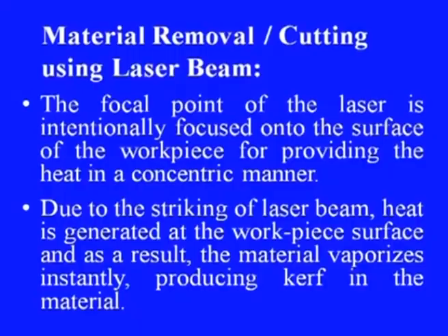It means the focal point is the point where we want to make a cut or make a hole in case of drilling. Due to the striking of the laser beam, heat is generated at the workpiece surface. As a result, the material vaporizes instantly, producing a cut in the material.